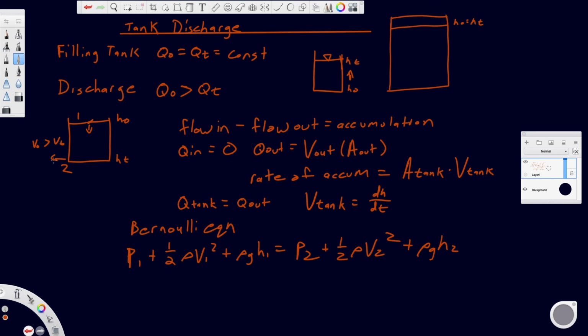So in a tank, obviously here we have potential energy at point 1, and then we have hydrostatic pressure at the bottom of the tank. Now, in a free jet, once this water discharges, it doesn't have a pressure anymore. So you're basically trading pressure for velocity, and going from potential energy to pressure to velocity, basically.